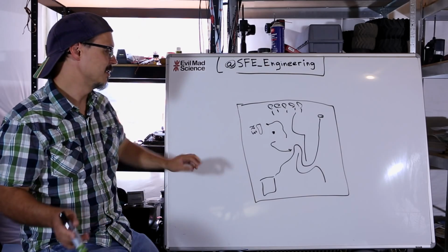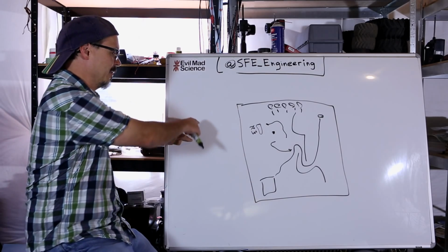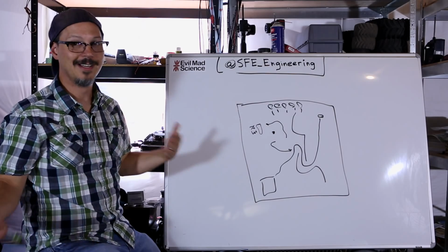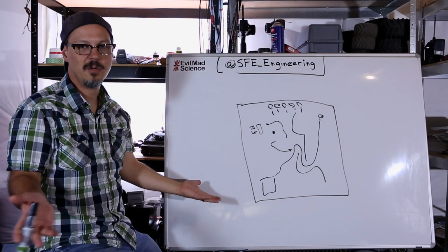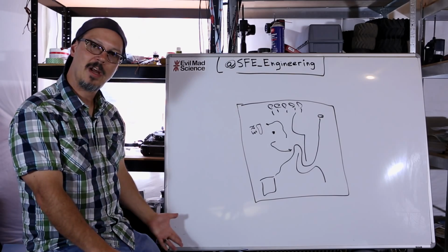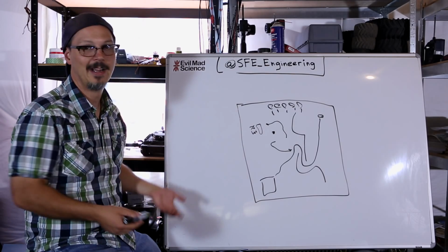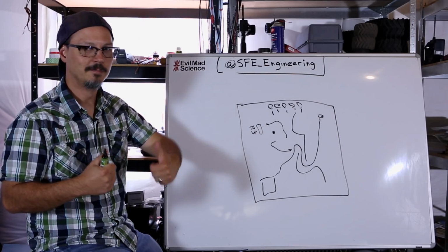Now, another way to do this is with a meter. You just take a meter and put it from ground to VCC and you check to make sure it doesn't say 0 ohms, or check various other places in the circuit. If it doesn't do what you want it to do, you've got to go back and find out why. And you might have to redesign, re-lay out, get in there, give them hell. So there it is. Hopefully I didn't add confusion to an already confusing topic, like I sometimes feel like I do.